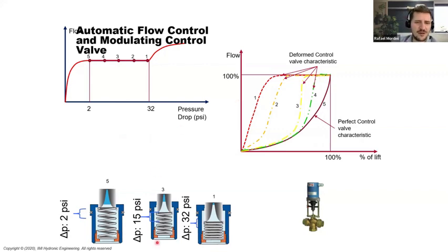And what happened? Well, the spring here will extend a little bit as well. The two valves will be working against each other until this here is fully extended. And this gets worse and worse as we get closer to the pump, or closer to this edge of this range here, 32 psi, right? Look at this case, case 1, when you're almost fully compressed. You're closing the control valve a lot and nothing's changing on the flow rate because the automatic flow control valve is compensating.